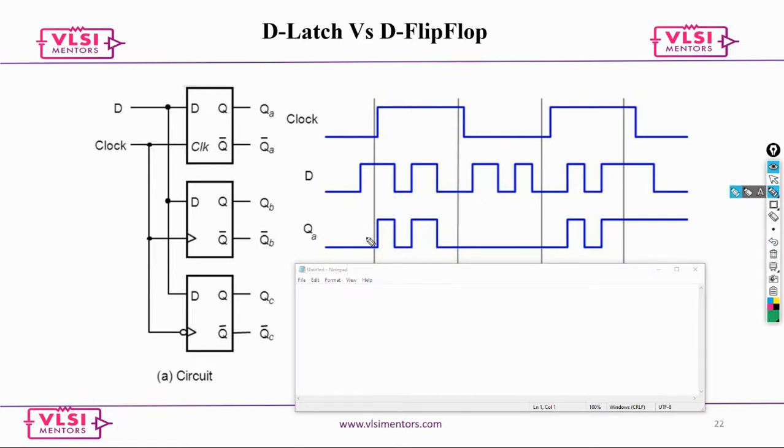As I said, the window opens during the rise transition, and the window closes at the fall transition, and whatever is there in this active period, when the signal is active, it would just be copied. Anything in the off cycle, when the clock is not active, will not be propagated or go through.